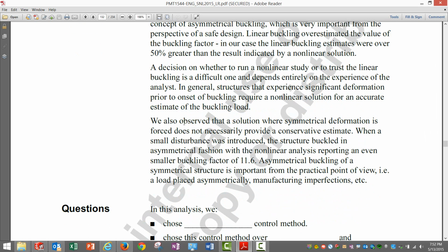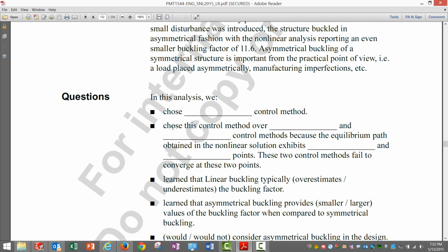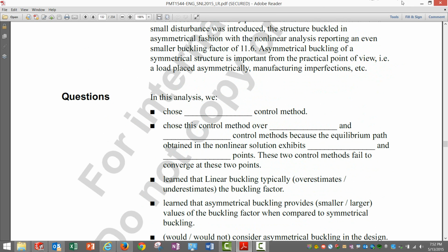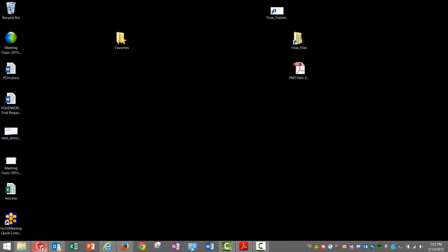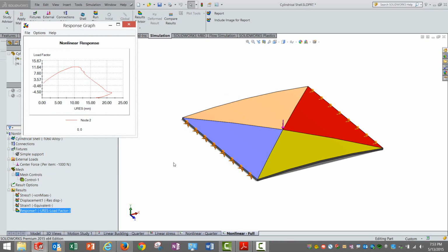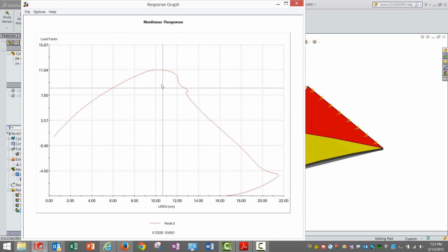As well, we got a feel of the linear analysis and how it can be used to find out the maximum displacement that a nonlinear buckling can experience. Okay, so the advantage of arc length: wherever such weird, funny or huge deflections are happening, wherein the graph moves from positive to negative and further, only the arc length method can capture such deflections.